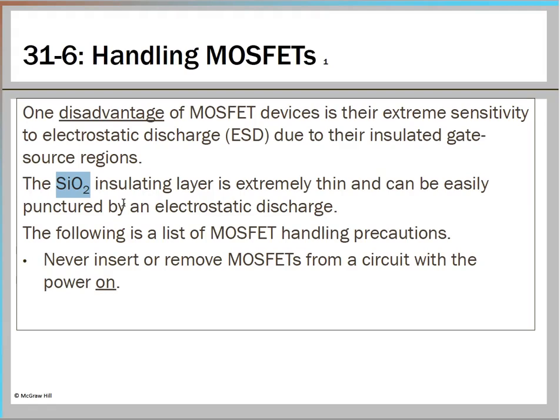If you exceed the voltage across the MOSFET, then even in just a few seconds your MOSFET will be destroyed. The typical failure mode for a MOSFET is a short between source and drain, if you apply a higher voltage than its rating.